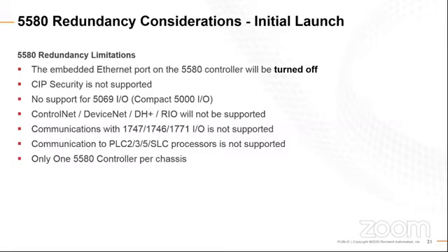For legacy communication, if we're dealing with ControlNet, DeviceNet, DH+, RIO, or the older controllers, that will not be allowed directly on an L8 style design. So we would still have to use either a simplex L8, tie that in and do producer consume, or we'd be looking at staying with an L7 style design for ControlLogix. So just be aware that this is something that is supported in the L7, and I'll talk about that in a couple of slides. But in an L8 design, we will not be able to incorporate DH+, RIO, ControlNet, or DeviceNet.